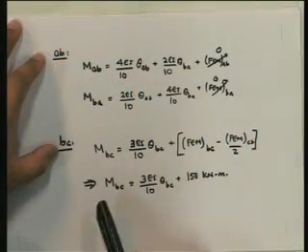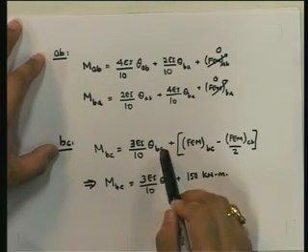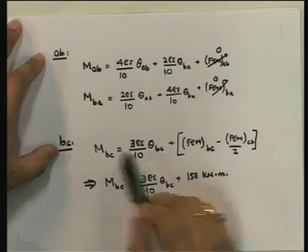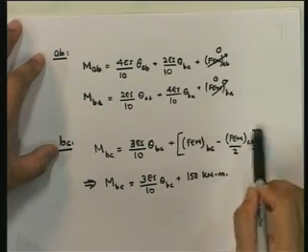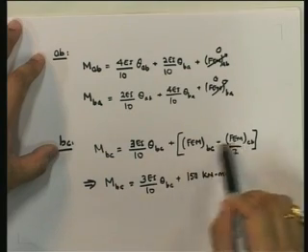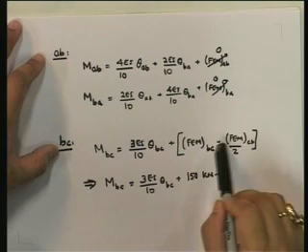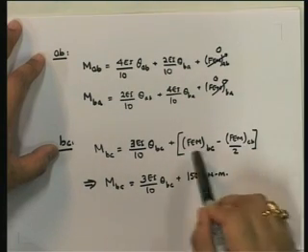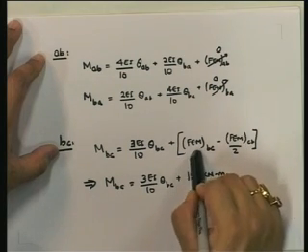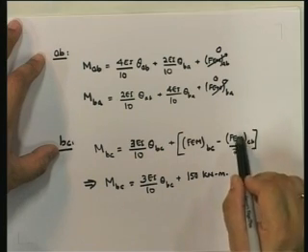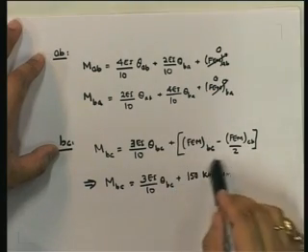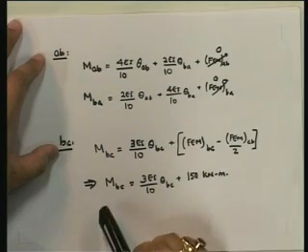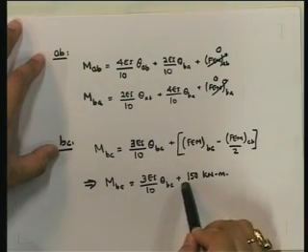Now here for BC, since BC is a modified member, MBC is equal to 3EI upon L, where L is 10 because it is 8 and 6, 10. Okay, theta BC plus the fixed end moment at BC minus the fixed end moment at CB upon 2. Remember this particular thing. Here, what are these fixed end moments? These are the fixed end moments in a fixed beam when the load is applied. Okay, remember that these two quantities we had evaluated last time. This had turned out to be plus 100 kilonewton meter, and this had turned out to be minus 100 kilonewton meter. So when you substitute that into this equation, you get 150 kilonewton meter. Okay, and therefore MBC becomes equal to 3EI upon 10 theta BC plus 150.